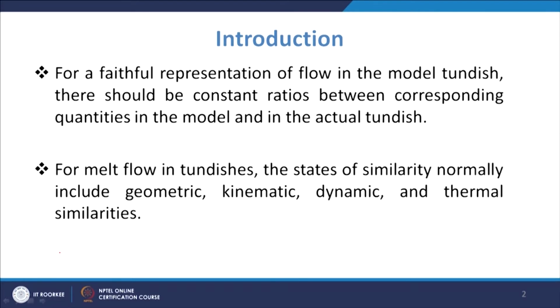So, you will have quantities like the velocity, the geometric dimensions, or the heat transfer values, which are there in the actual tundish and in the model tundish, and all of them need to have a ratio. That should be maintained for the model and the actual tundish.